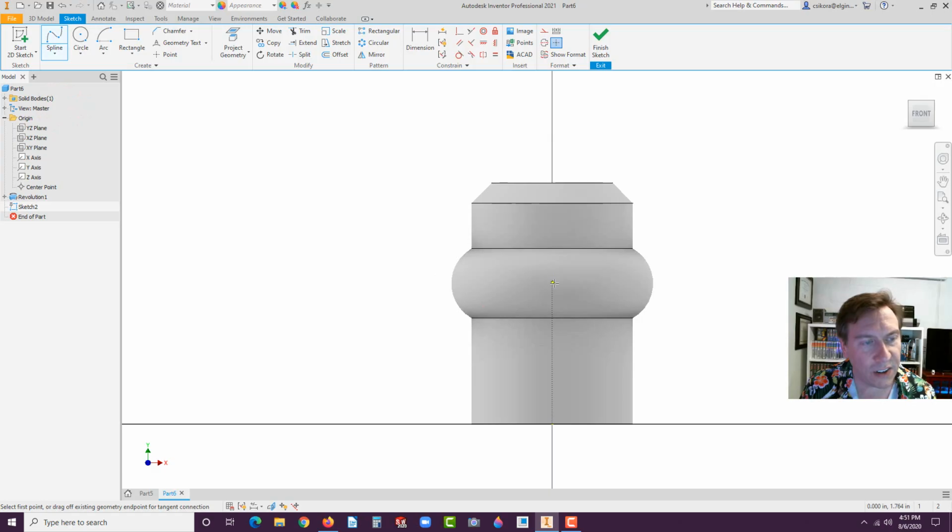Move your pointer to the center, and you'll see you can infer to the center, but not really the center of the hub in the middle. So right about there, just click. Now drag this out and maybe infer to this edge, and you'll see the center point appear. Click on that, then click on this point, and now I'll start dragging it up. And I'm just clicking and adding points, and these control points are going to make my curve look interesting. Eventually, when you get about a half dozen, 6 different control points, and it looks similar to mine, go ahead and hit OK.